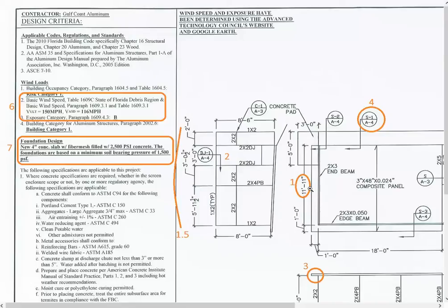So what happened to the 25 inches that would be required to make this 14 feet? Well, that's simply the overhang on your house. Most houses have a 2 to 3 foot overhang, sometimes as little as 1 foot. Sometimes some older houses will have no overhang, but most houses have an overhang. So this house had a 25-inch overhang. So when you have a 14 foot pad that's going to be your footprint, subtract the 25 inches that the house's roof overhang is covering, you're down to 11 foot 11 inches.